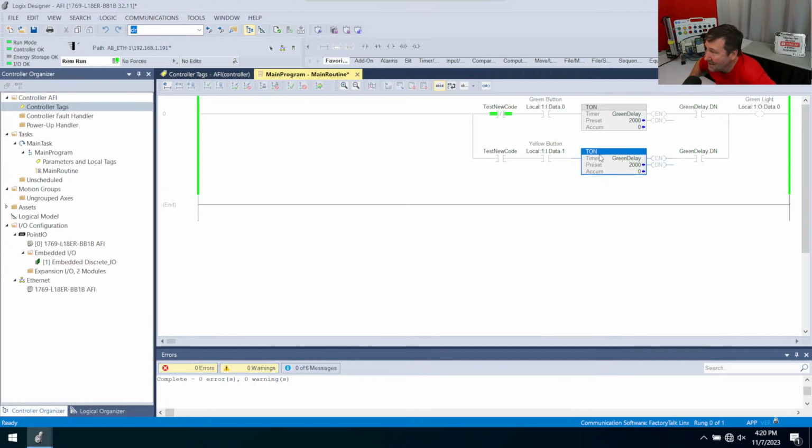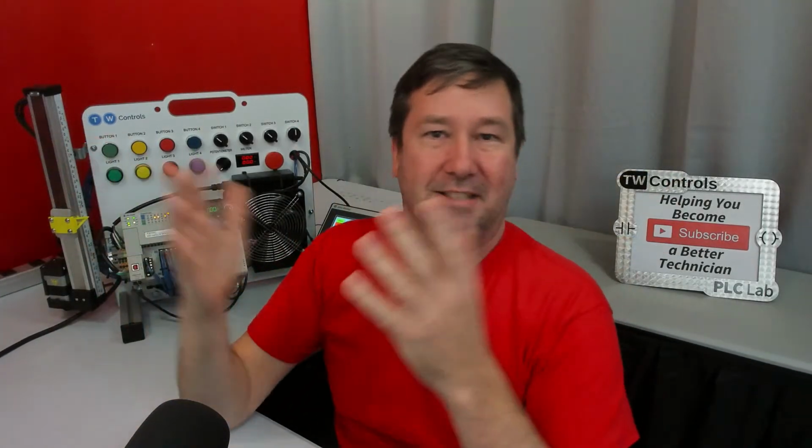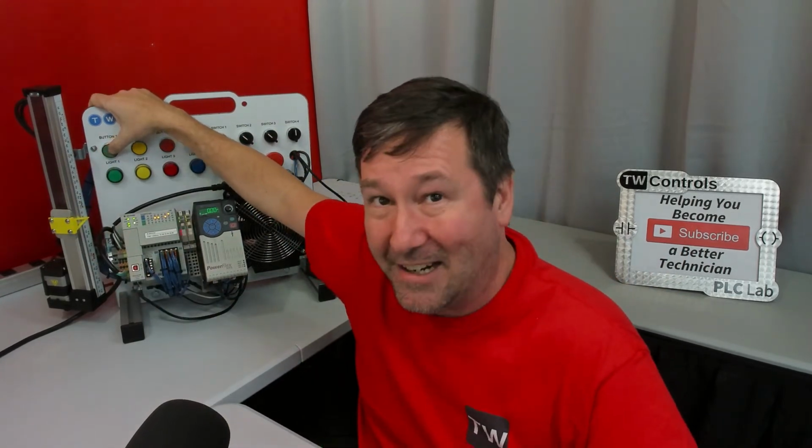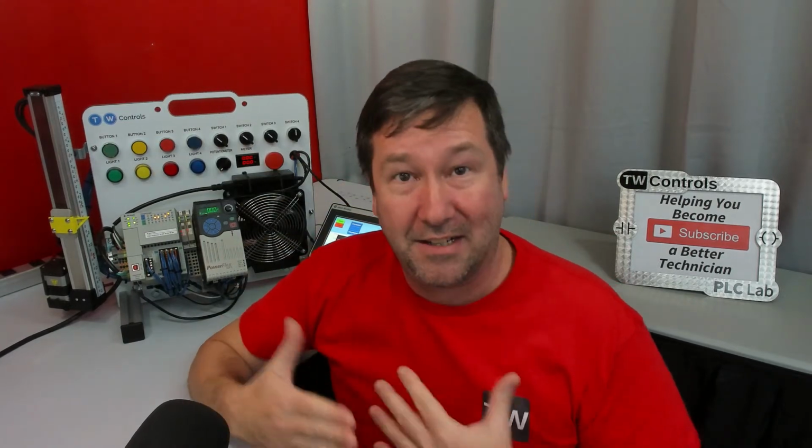It still continues on, and when it gets to this TON, a false TON goes and writes a 0 to everything but its accumulated value. And that includes this enable bit, and this done will never happen. And you send me a lot of your code out there where you're like, hey, I'm trying to test this stuff out and I can't get it to work, and I look at it and I see this exact stuff where you get a branch and you've got a double timer.